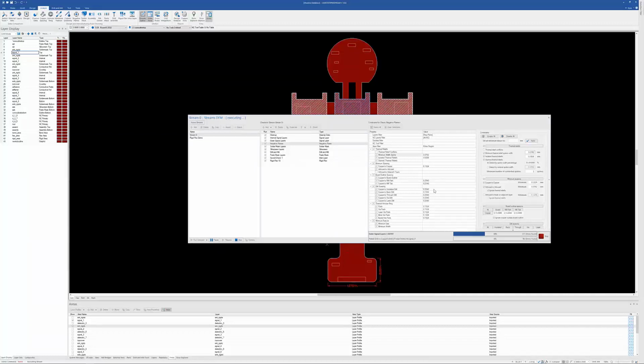Like if you wanted to change drill spacing, and you see I've got different values there, I could go to drill spacing over here and change them all at one time to a certain value if I wanted to, or do individual values. So I've got the spreadsheet mode, or the matrix mode, as I like to call it, over here. Underneath all this is filtering, so you can filter in and out by decode, layers, areas, NC tools, NC layers, and filter those in and out when running analysis as well. So very robust ability to run the analysis.